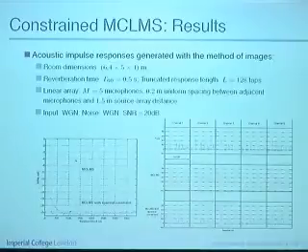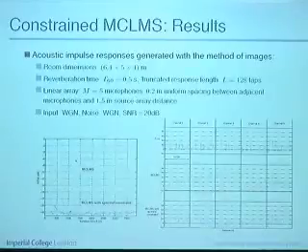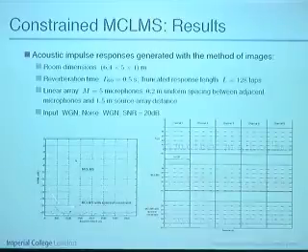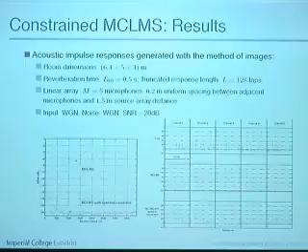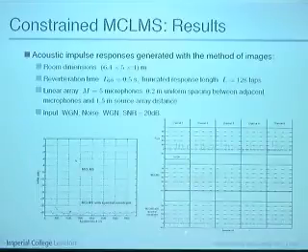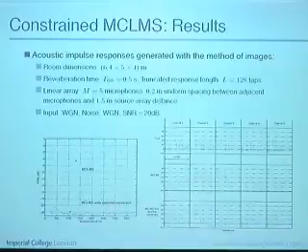So here you have the misconverged solution using just the standard time domain adaptive algorithm. And if you impose the spectral constraint, you actually manage to stabilize it, although you delay the convergence a little bit. And the same effect you can actually see with the direct path component substitution. They both work in the same way. And here you can see the estimated channels, which correspond quite well to the original ones.